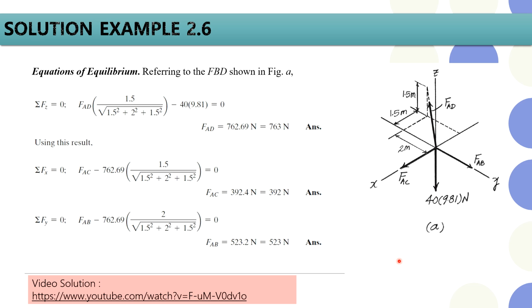For coplanar or 2D problems that we have learned just now, you need to sum the forces in the x and y directions. For 3D problems, you simply add the z direction and need to use Cartesian vectors to keep everything organized. In your final calculation, if it gives you a negative force, don't worry. It just means the arrow on your diagram is pointing the wrong way. So instead of positive, it will be in the opposite direction when the calculation gives you a negative force.